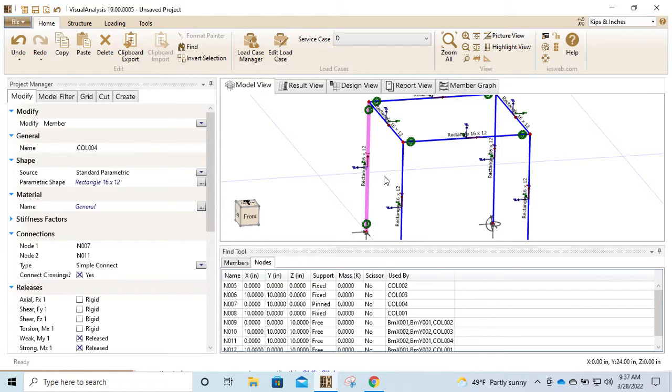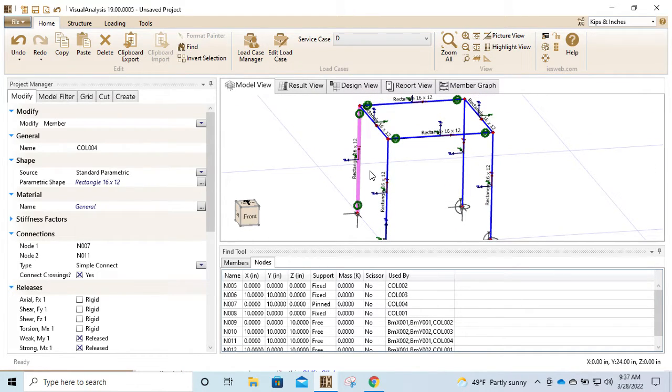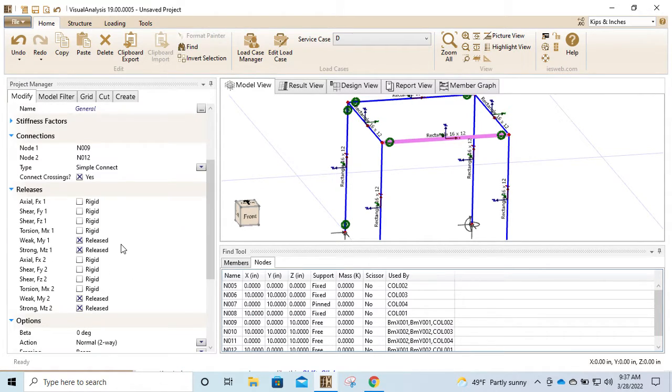Because, what's that? I did, and then I made it pinned to show Elias why pinning it and releasing it are bad. But pinning it, like, I guess I'm thinking about the axes, is it assumes when you say simple support, like on those beams, you say simple support and it knows which axes should be free to rotate and like along its axis, I guess. When you do simple support, what it ends up doing is it releases the strong and weak axis, right? You could go through and say, this gives you a fast way of imposing all of these releases.